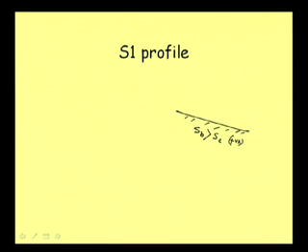And when it is greater than SC, our normal depth line will be somewhere here, say NDL, and the critical depth line will be above the normal depth line. This is the CDL. Now, when we talk about zone 1, that means the profile will be here, and so this is our y.